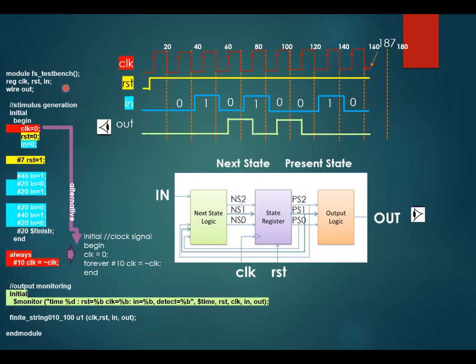Okay, so you just need to use variables to connect the testbench stimulus and output. In this case, you write the testbench to produce the signals clock, reset, and in. You're going to write them using a sequential block. You have learned before, always is one of them. Initial is another sequential block. Whenever you use initial or always, whatever signals are produced must be declared as type reg. That's why you put reg for clock, reset, in. Why type reg? Because you're going to use a sequential block, which is initial here, to produce the signals clock, reset, in.